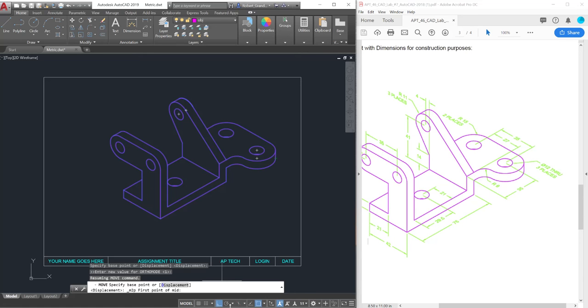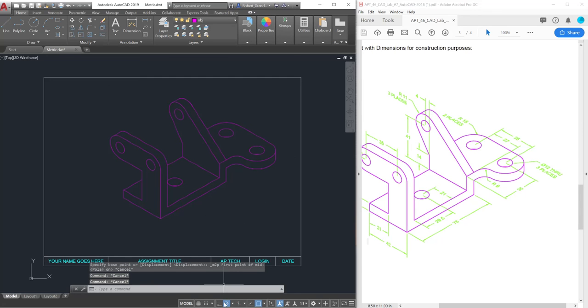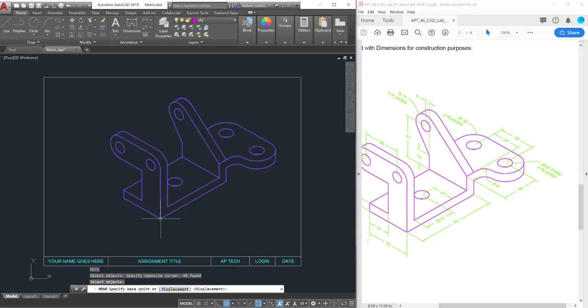oh, my polar mode's not on. Let me turn polar mode on. There we go, object track, down, and oh, interesting, why is my object tracking not working here? That should be working fine. Let me stop that, and I'm going to make certain polar mode is set to, that's why, every 90 degrees. And then we'll do that again. Move these, pause, move away.